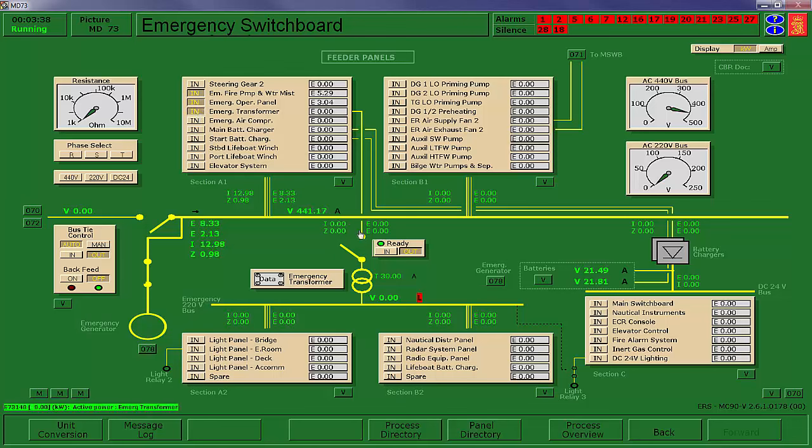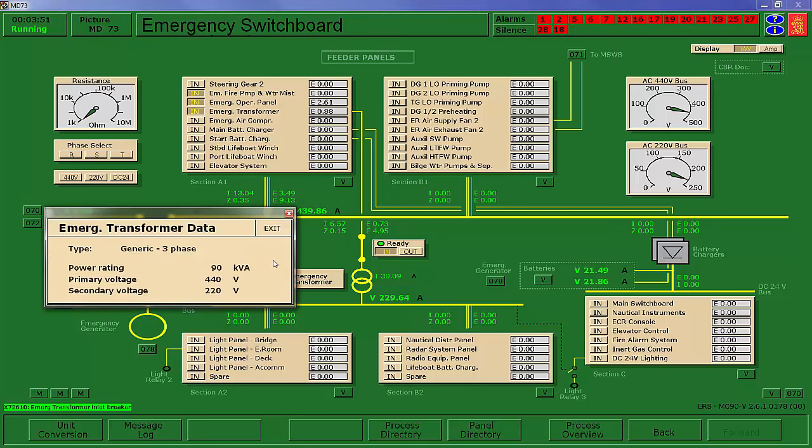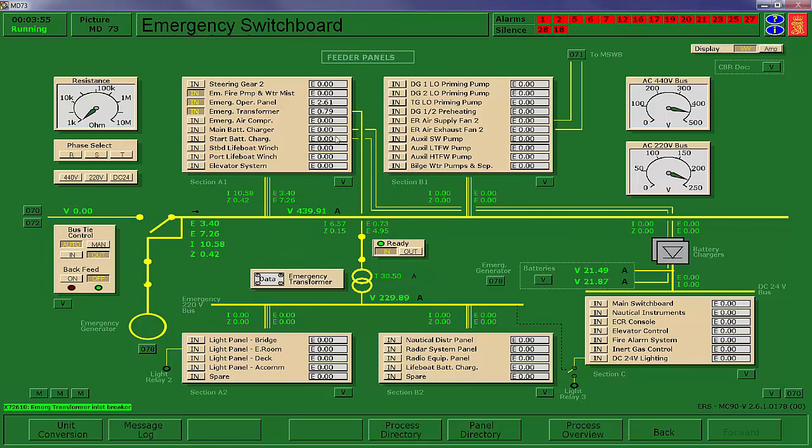That, by the way, energizes down to, this is an air circuit breaker again, it's motorized, and that green light tells you that its springs have charged. And that is for our lighting transformer, and it is a 440 to 220 volt step down transformer. And that was energized off this emergency lighting, or they've shortened it, emergency lighting transformer.